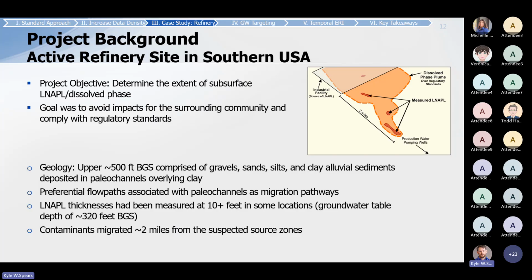So some of the wells had measured 10 feet of LNAPL thickness, and again, the groundwater table wasn't even till 320 feet below ground surface. So big issues to solve here.